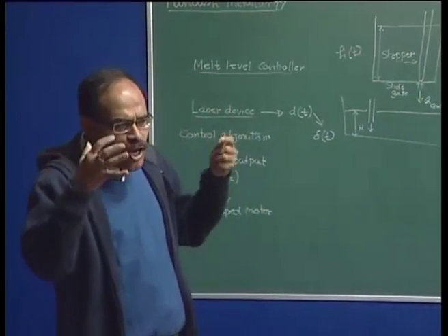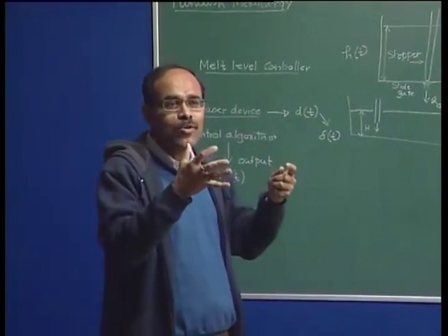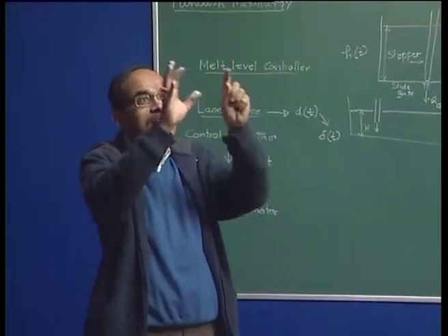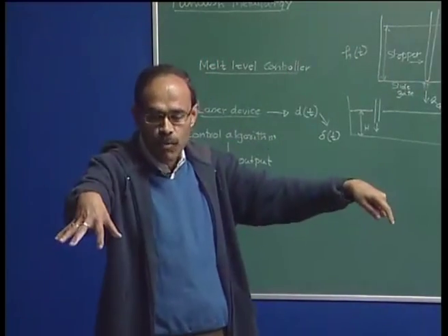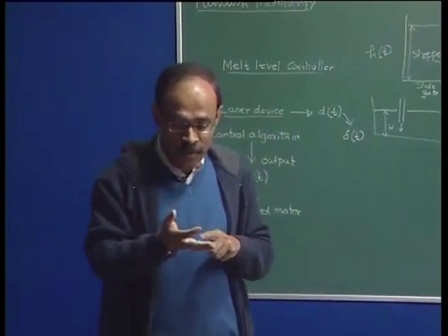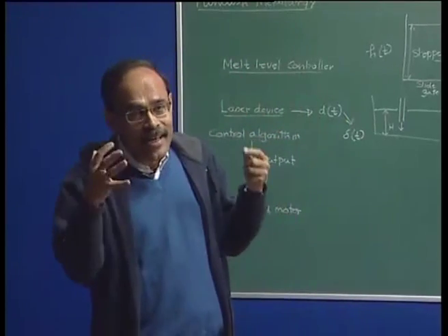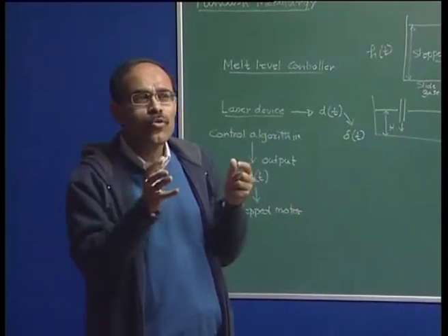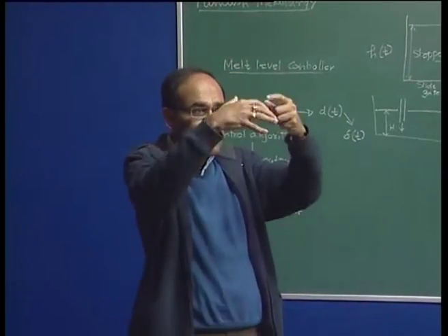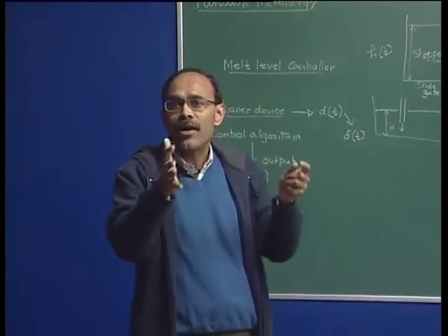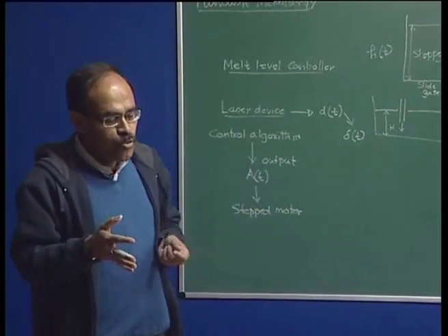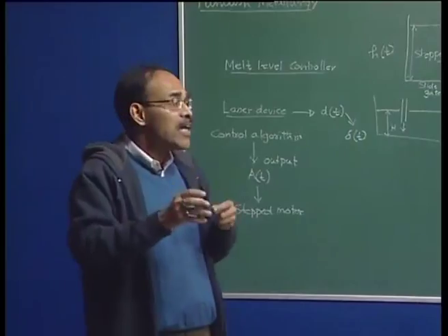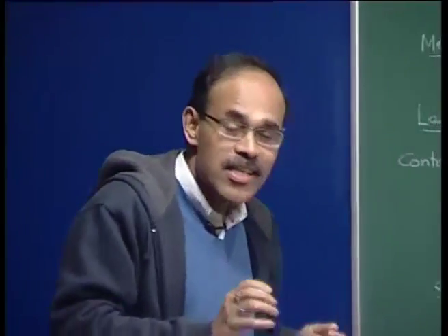So, there is a lot of scope in tundish metallurgy also. We need not look at the tundish just like a distributor to two different molds. No, it is not like that anymore. We have a lot of scope there, and in the tundish we can virtually maneuver the operations by controlling the design of the tundish, introducing furniture to such an extent that the productivity and the quality of steel can be significantly enhanced.